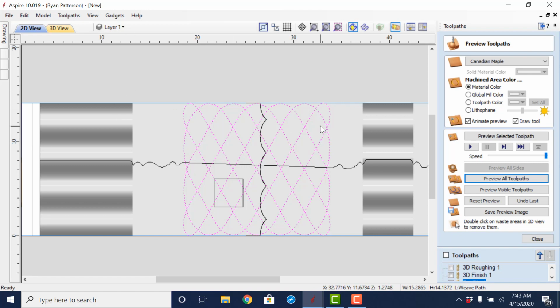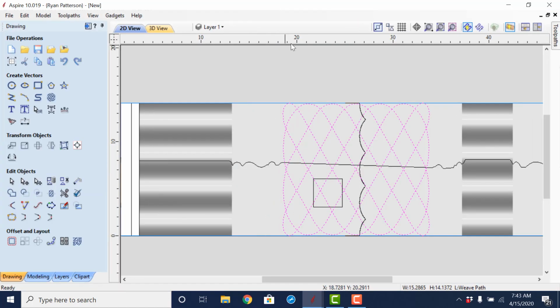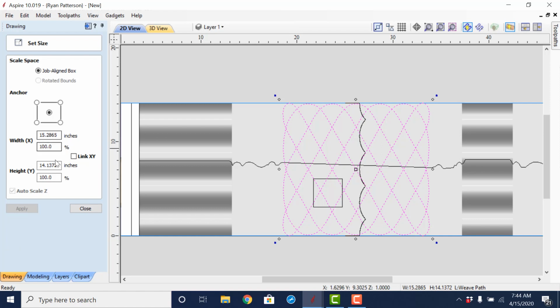So what we're going to do is, with that selected, come over and change, we did not need the help button. Click the toolpath tab. We're going to scale this back down to half the size of the Y. Again, we could bring out a calculator and do the math, but I could just do that divided by 2 and then hit the equal sign.